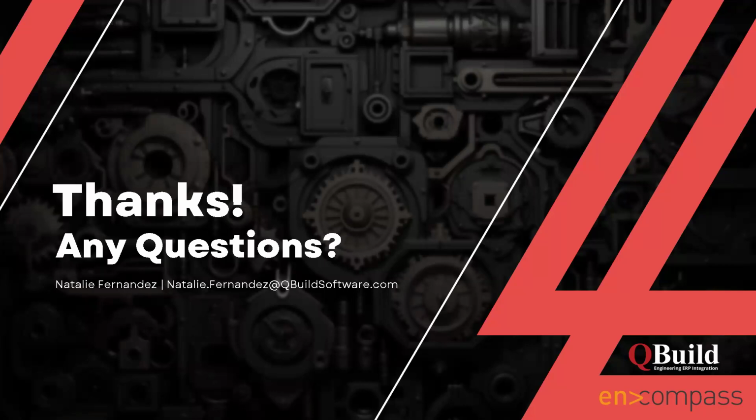Ryan also asked, how would CADLink handle configurations in SolidWorks? The answer is CADLink takes the active configuration. So whichever configuration is open when you launch CADLink, that is the BOM that CADLink will take when pushing to Epicor. If the fasteners are modeled in SolidWorks, then they will appear in the BOM automatically. Then it won't need to be a manual part, it will just be a regular part.